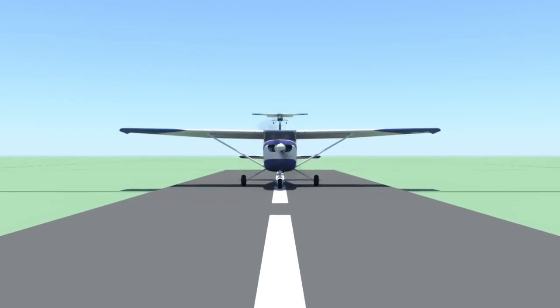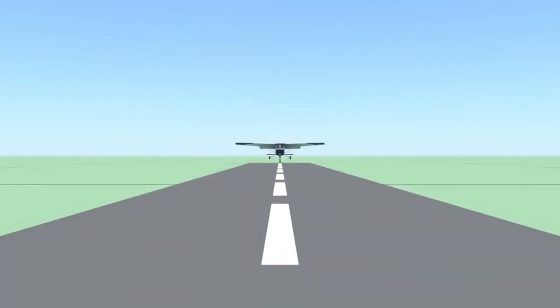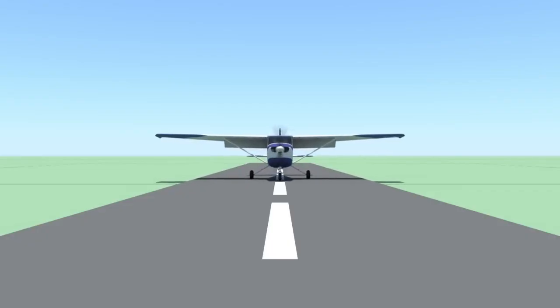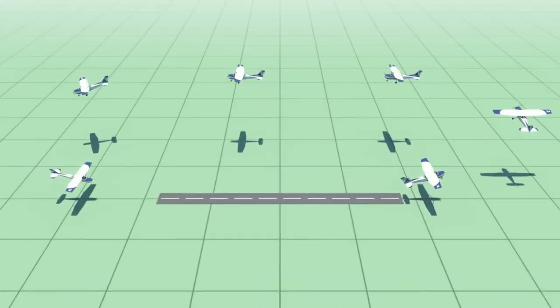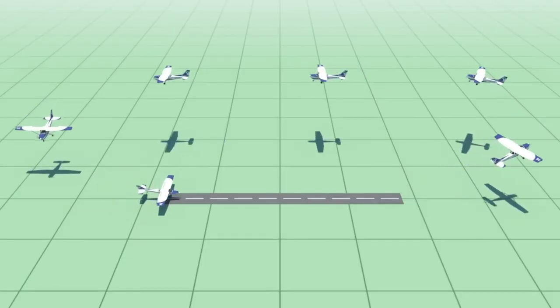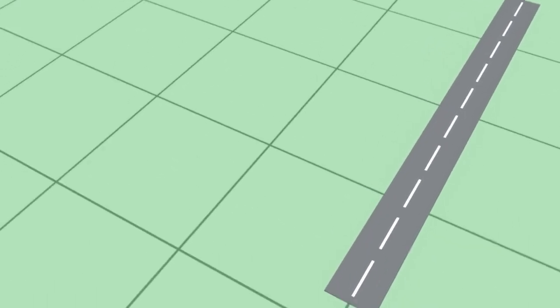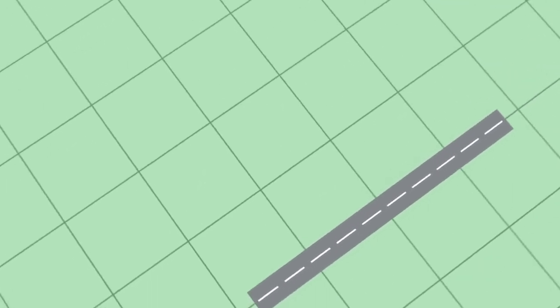When taking off or landing at airports, pilots use a standardized traffic pattern. The traffic pattern's main purpose is to ensure that air traffic flows into and out of the airport in an orderly manner. This makes the airport environment safer since all aircraft should be following the same procedures. The basic traffic pattern is similar at all airports, whether it is controlled by a control tower or a non-towered